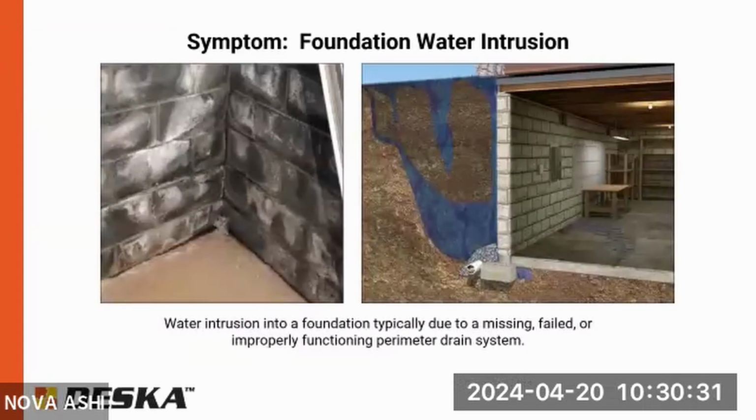And then waterproofing. So we have our exterior drain tile here. It's very important that that drain tile be there. Older homes, many of them don't have it. But if water is accumulating around the foundation, downspouts aren't functioning, and the water is not getting managed and taken away from the house, there's a lot of pressure on that wall. You can have water intrusion issues, and then again, you can have your inward lateral deflection, amongst other issues.